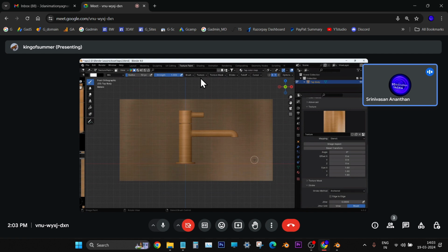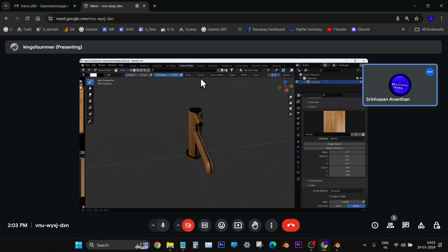Right now you see, just middle mouse button and just don't move it. That side also it got painted. That is why we did the XY on. Right now go back. This is Z. Yes, very good. Now go to right view, press 3 on the keyboard.